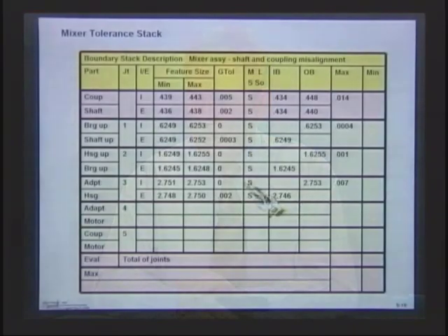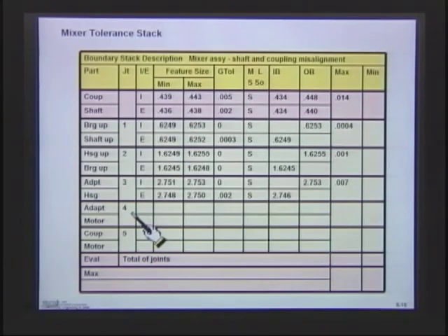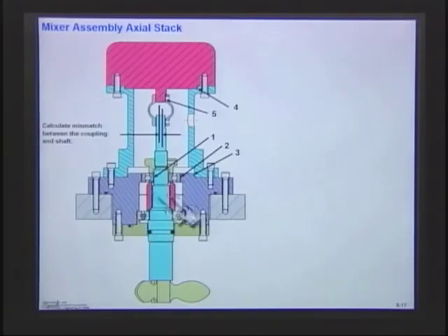All right, let's take a look back here. So we had 7 thousandths on that joint. That was 3. Now we have to go to joint number 4. So let's travel over to joint number 4. Joint number 4, we had pre-labeled these. Remember, if you're doing a stack, you want to label these so it's very clear. Now we have the electric motor and we have the adapter. This was a purchased electric motor, so we'd have to find out what kind of tolerance they're going to have on that. We didn't do anything with that, but this was our part that we had toleranced up.